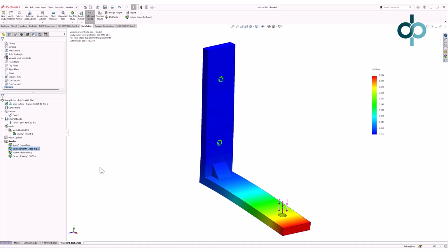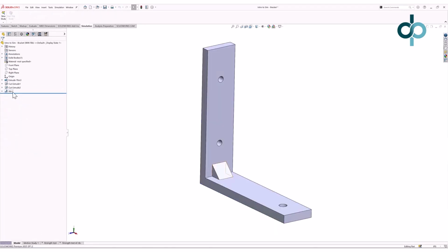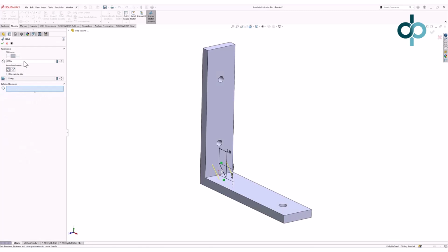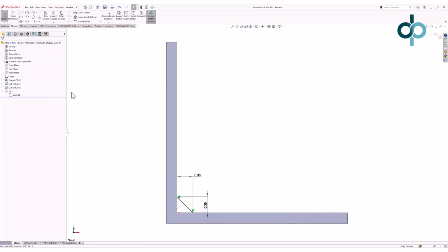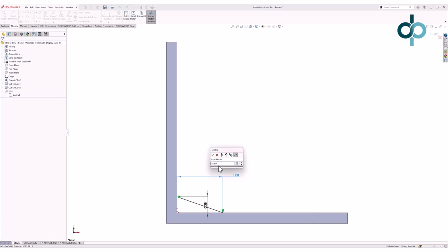And you know what? By doing that, iterating on this model multiple times, tells me something interesting, that the rib thickness might not be the critical factor here. Instead, let's try to modify that rib geometry and let's get crazy with it and change its location here on the bottom to be, instead of 3/8 of an inch, let's just click that, drag it, move it, and go up to, I don't know, let's say 1 inch.